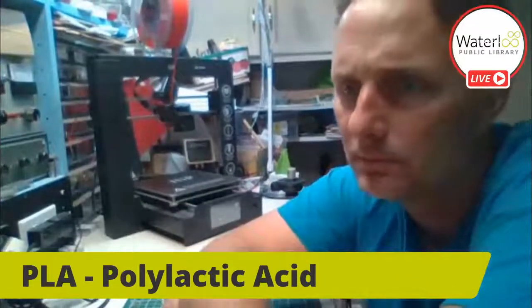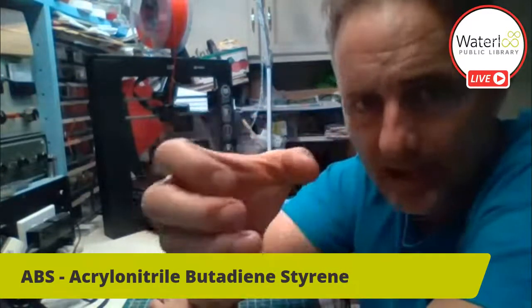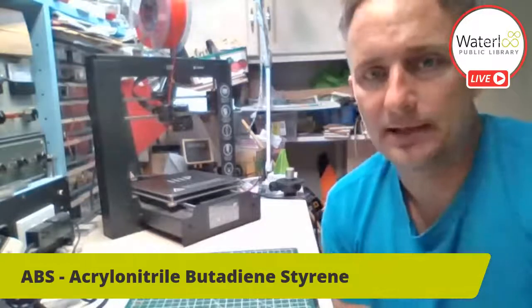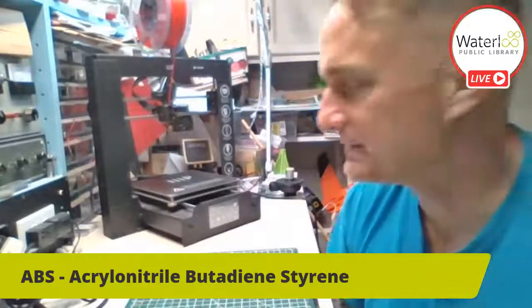Another very popular material, ABS, acrylonitrile butadiene styrene. It's that same stuff that's in your drain pipe under your sink. The black plastic tube is ABS. It's another very popular, very inexpensive plastic that people use with 3D printers. It is a little bit more rigid and stable and harder than PLA. So it has slightly better dimensional properties. And it's also fairly chemical resistant to a lot of materials. Like I said, ABS is in your drain pipe, and you flush lots of things down the drain every day. So it can hold up to a lot of stuff.